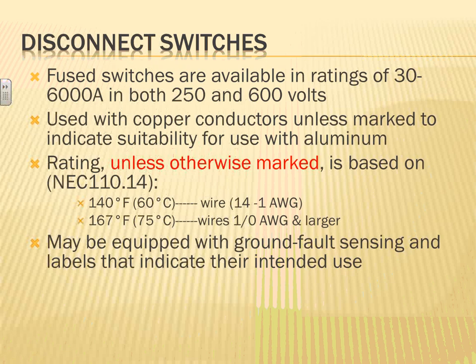My understanding, correct me, you guys are all engineers, is that this comes from UL listing. So equipment more than 100 amp requires lugs rated for 75. Less than 100 amp, it could have 75 or 60. So unless they tell you it's 75, the assumption is going to be 60. Who cares? When we size conductors, that becomes a decisive factor in terms of which column I am going to use. If you're dealing with three-phase equipment, almost always it's rated for 75, so you don't have to worry about that one.